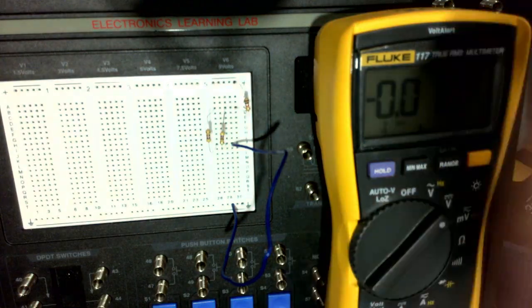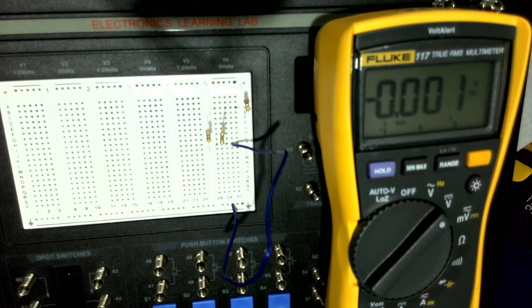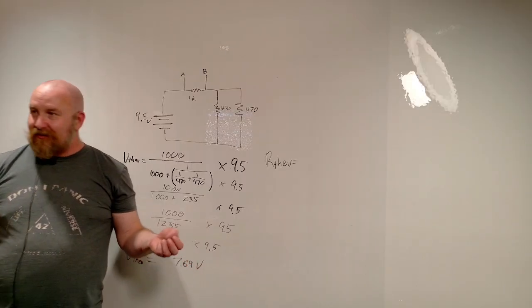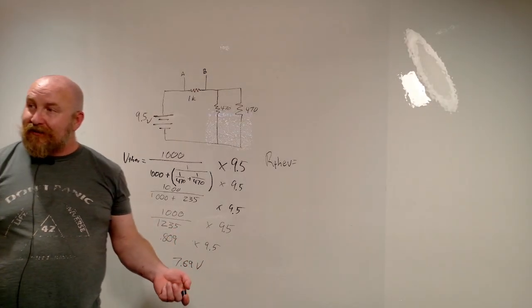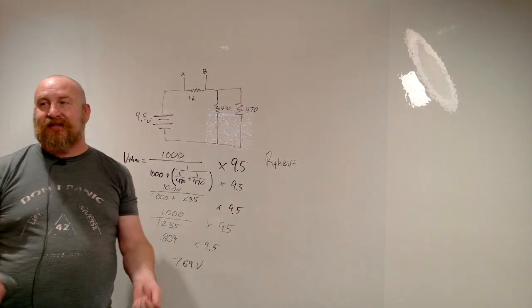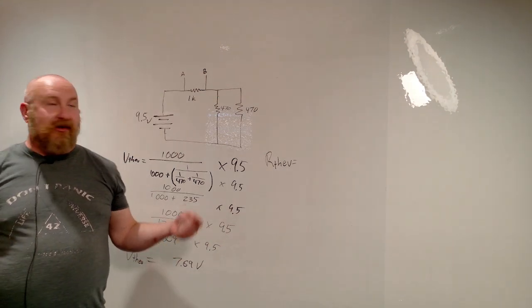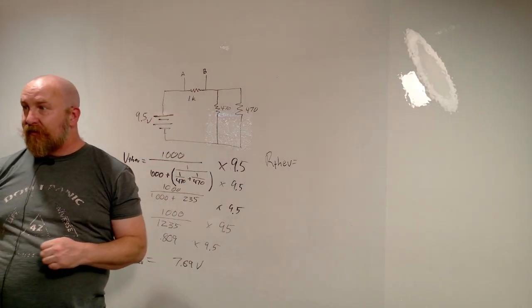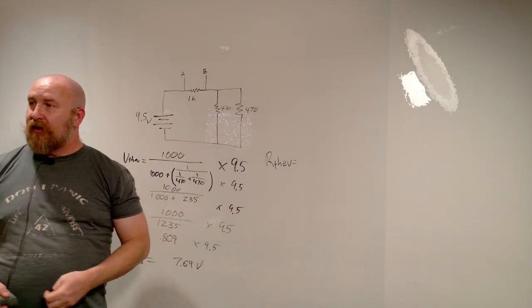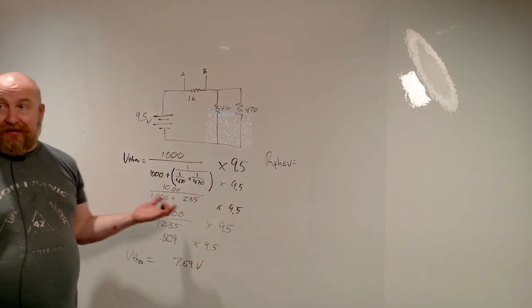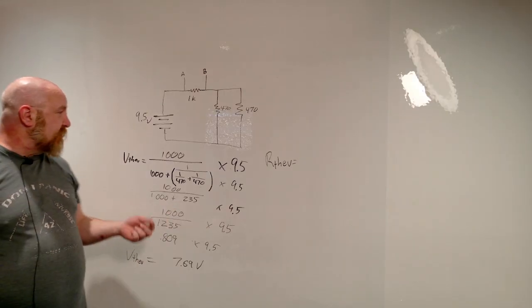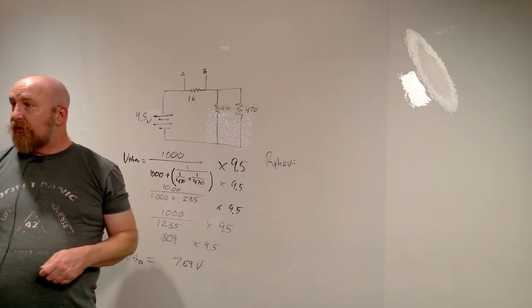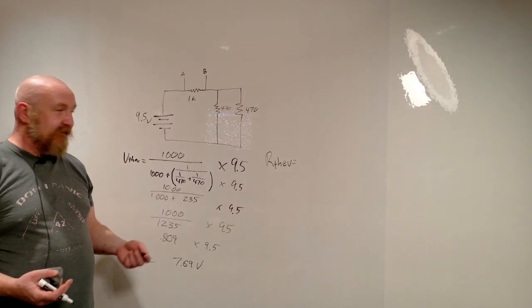Really close. So this is how you know what voltage you should be reading when you go and touch two things in there, right? It's not the whole 9 volts, because there's only a portion of the drop that happens here. The rest happens here. Pretty simple, right? And it's just really creating a fraction of the whole. That's how you find VThev.